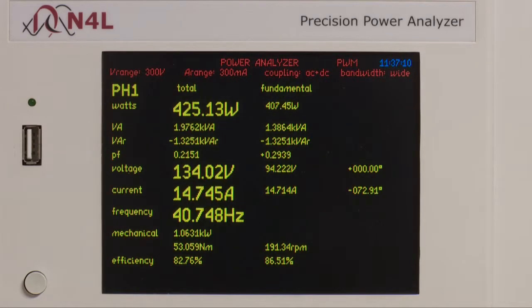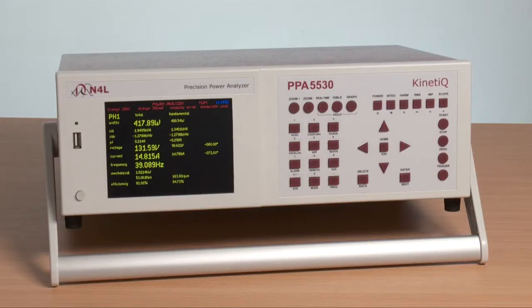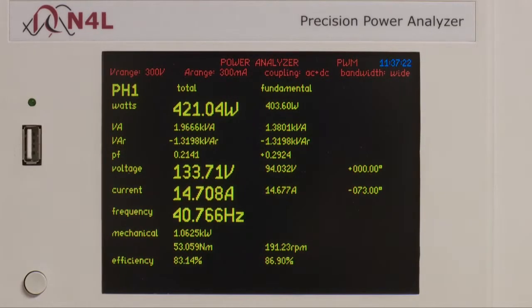So, we have approximately 10 volts difference due only to frequency components above 30 kHz. Since switching frequency components are present in both the voltage and current signals, it is clear that filtering will reduce the accuracy of wideband measurements.